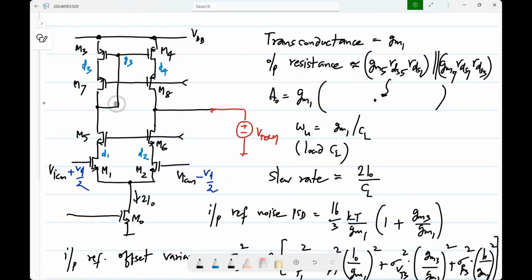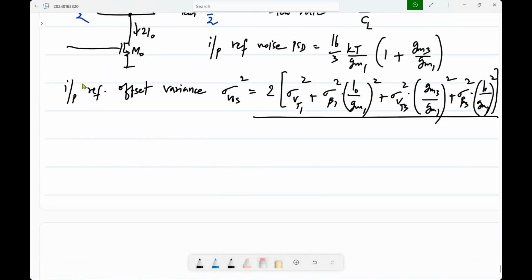And actually, this part is complicated because there is some parasitic pole and there is also a feedback loop around it. So this has its own behavior, right? It's not just of the form GM by something. It has its own parasitic capacitance. So this feedback loop will move the poles within this loop and so on. But we won't worry too much about it.